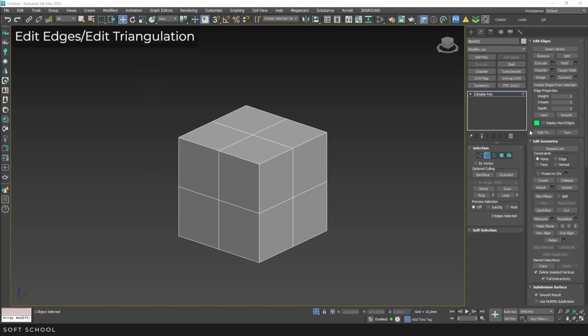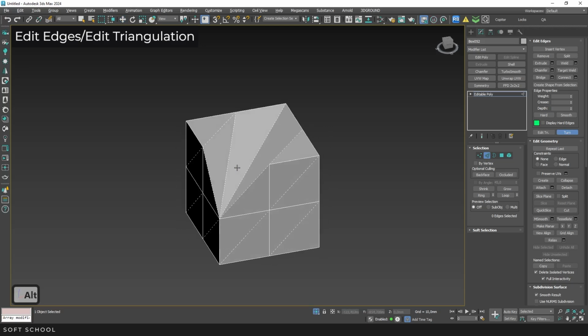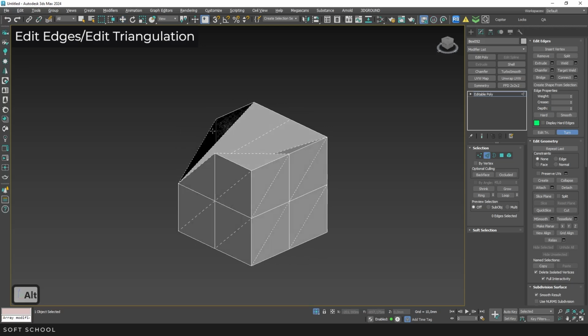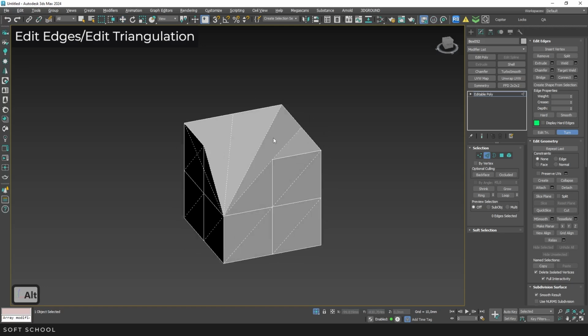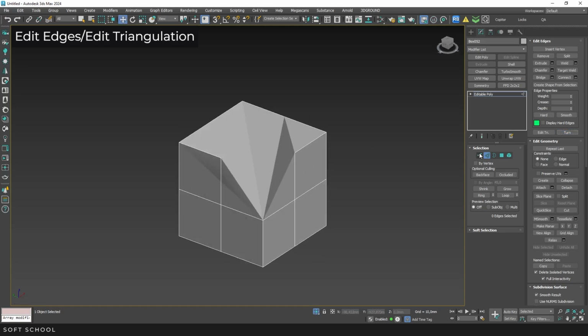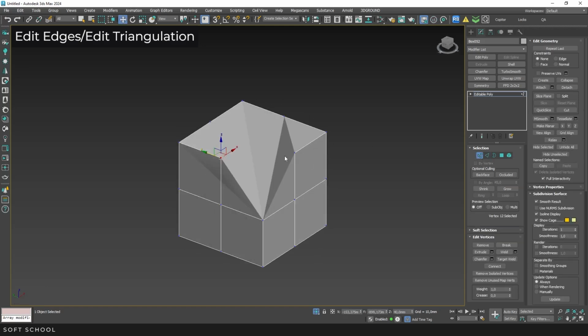The Triangulation Adjustment tool enables manual editing mode with the left button and allows simplified flipping with a right click. Why is this needed? Mostly it isn't, because a correct mesh excludes the appearance of overlapping polygons or artifacts. But if it happens, this tool helps fix errors so they don't interfere. Though it's better to restore the mesh, which takes longer but yields better results.